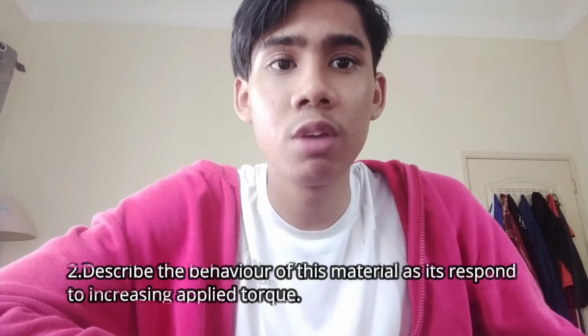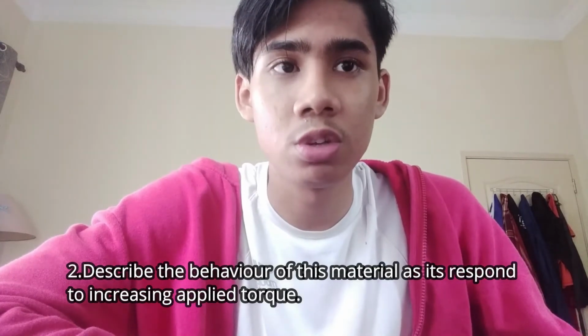So based on the modulus of rigidity, the value is smaller, with an error of 1.5% compared to the original. It is because the steel has very low ductility. For the Poisson's ratio, the experiment value is lower than the reference value, which is 0.29. For the shear stress, we can see that it is a little bit different from the reference value. Also the same for the shear strain, where the experiment value is very low because the specimen is brittle.